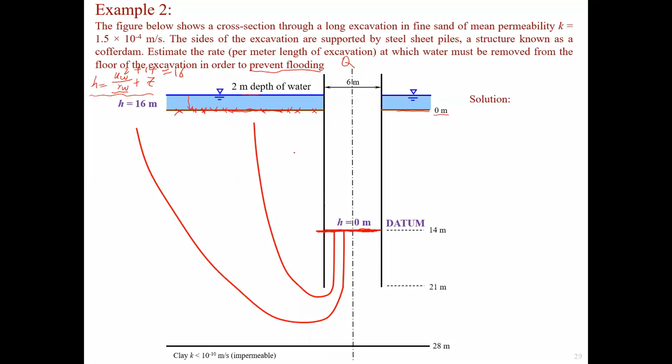Your equipotential line will meet the rule. I will explain later on. Now let's look at only 2 flow lines. If you would like to draw the equipotential line, so that's the first equipotential line. That's why we plot this way, because we have to meet all these requirements. They form a right angle with the flow line. So that's the right angle.